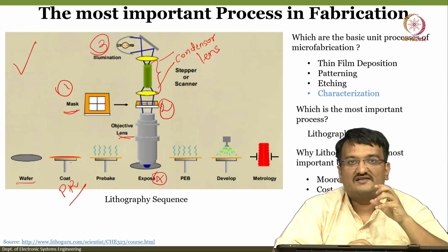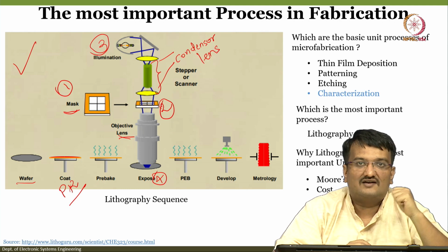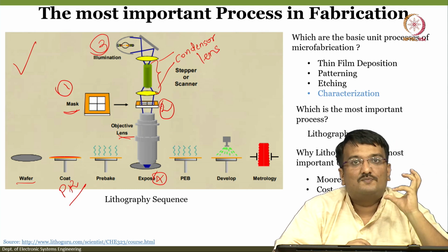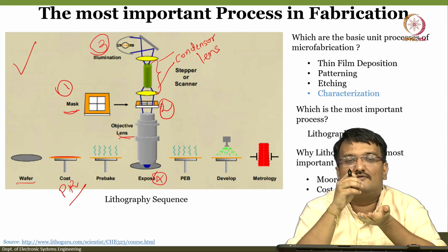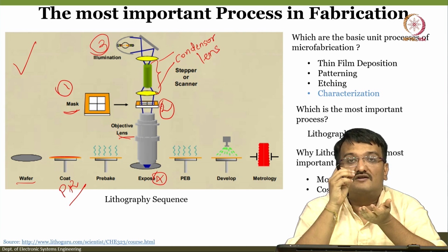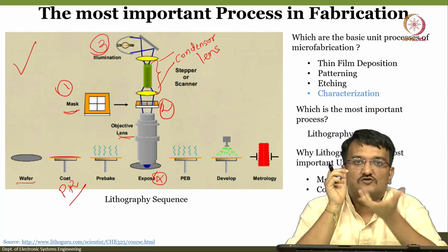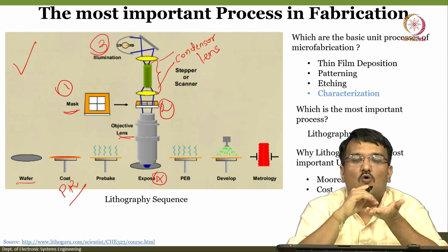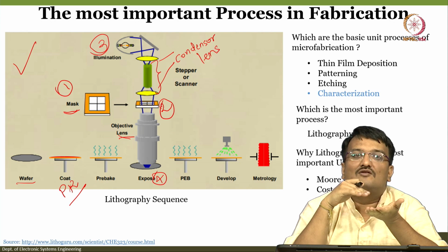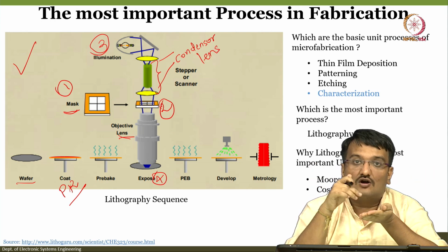Now PR is photoresist, which is coated by something called spin coating. If time permits, we will show the demonstration. A spin coater coats your photoresist, which is a semi-liquid chemical with a finite viscosity. So when you pour it on the wafer and spin coat it, your spin speed will decide how thick your PR will be coated, and that is already calculated prior,